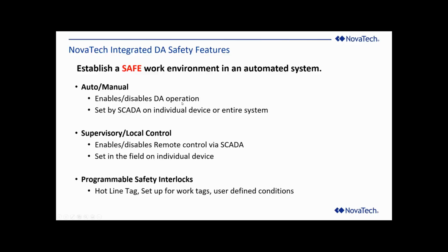The auto manual is a logical input, and does not exist generally in the points of a switchable device. So that is a virtual point that is created in logic within the Orion using Logic Pack or using Lua or some other mechanism to be able to turn that on and off.